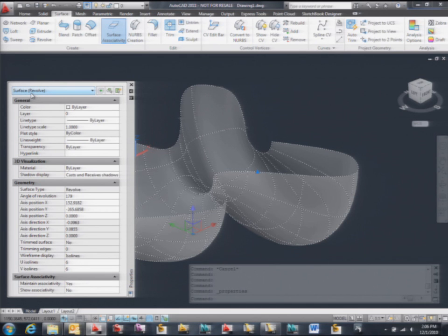So how many of you are familiar with the concept of NURBS surfaces? Some, okay, a little bit. So a NURBS surface is basically, at the end of the day, this is a NURBS surface, right? But it has a wrapper on top that tells it, okay, you are a revolution. So you just remember where you came from, and honor that origin, right? If you're just a NURBS surface, it is only edited based on the grid of U's and V's in both directions, right?